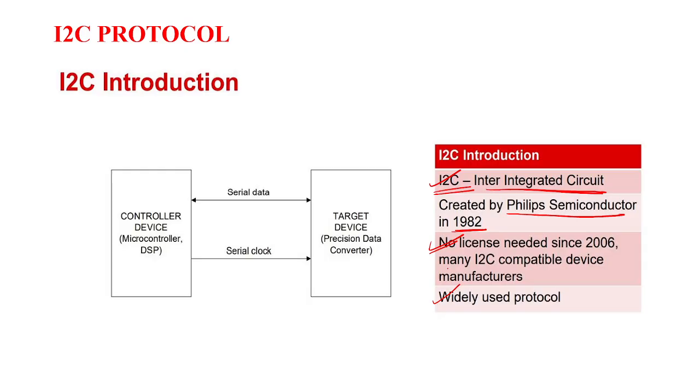Mainly it consists of a master and the target devices, which are slaves. The master can be a microprocessor, a microcontroller, a DSP, or an FPGA. The slaves can be different types of low-end peripherals.